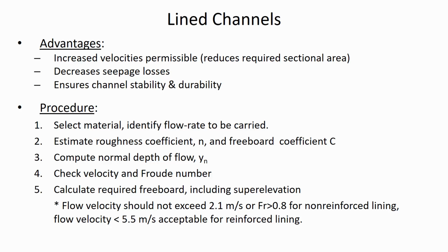The procedure for designing a lined channel is to check and see what material you have available to define the N value in the first step, and identify the flow rate to be carried in the second step. And that's not always a simple process, because all hydraulic systems are going to eventually fail. It's just a matter of how frequently you want them to fail.